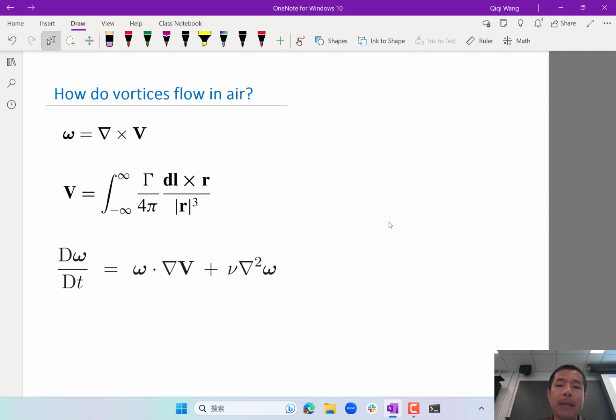So what we have learned in unified is basically that in a uniform flow field, the vortices just go straight back behind the wing, assuming the flow field behind the wing is actually free stream, right? There is no induced flow. Then we can calculate that the vortices just go straight back. But there is a contradiction here, right? There is induced flow by the vortices. So the flow field behind the wing is not going to be uniform. And we did not learn how vortices behave in a non-uniform flow field.